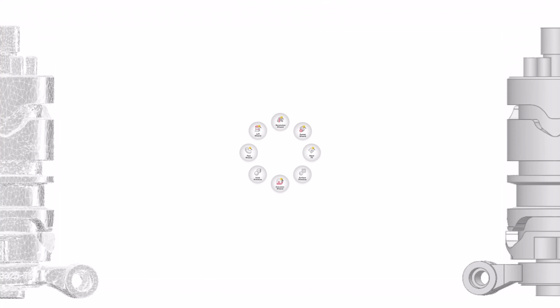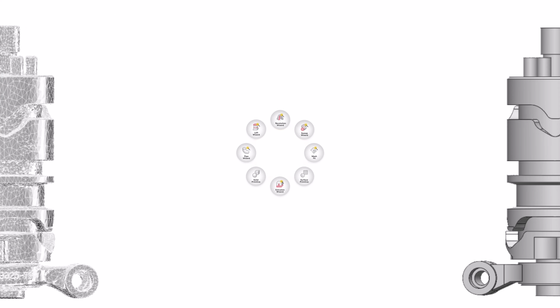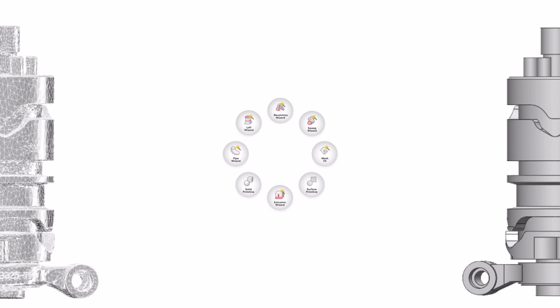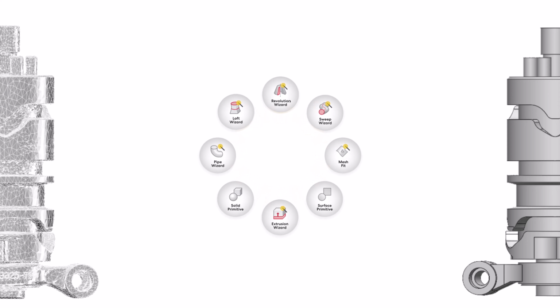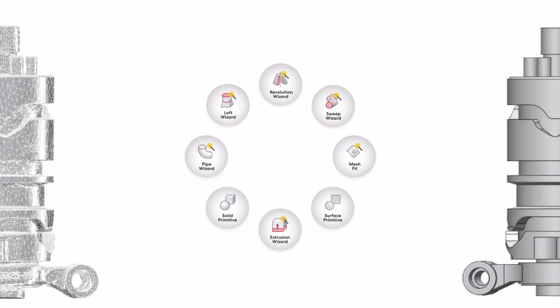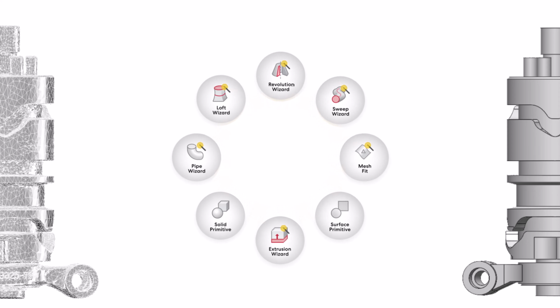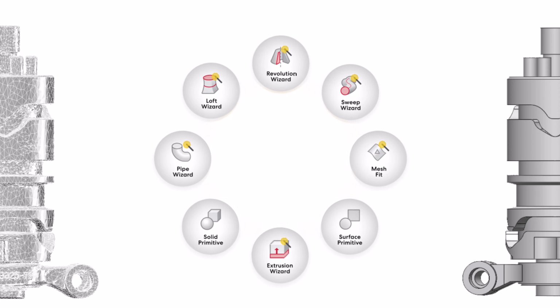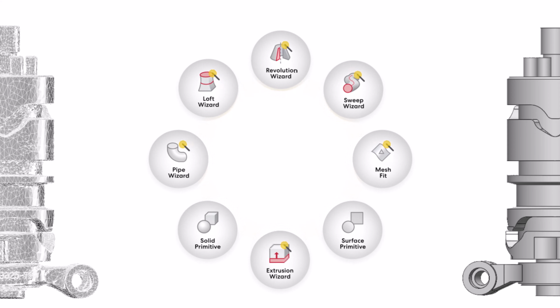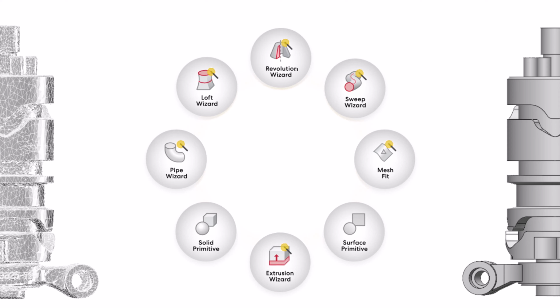The modeling wizards in DesignX are the closest anyone's ever come to the holy grail easy button that converts a 3D scan into a fully featured design intent CAD model that functions seamlessly inside your existing modeling software. If you have a good grasp on how to break down your scans into their existing extrusion, revolve, sweep, or loft features, these tools can save you a ton of manual work. They're a big part of why DesignX is the fastest path from scan to CAD.